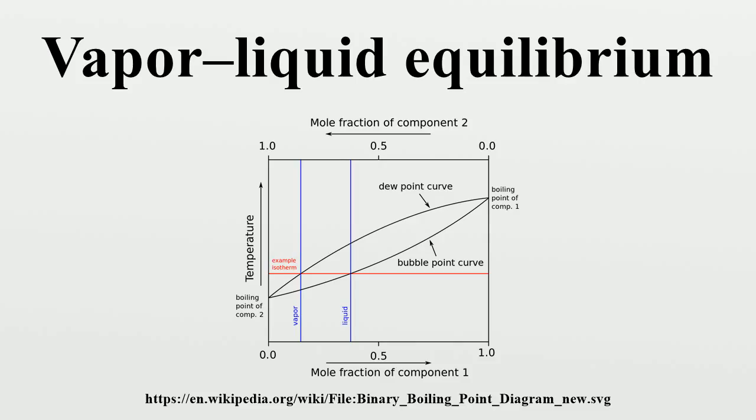When this is finished over a complete range of liquid mole fractions and their corresponding temperatures, one effectively obtains a temperature T function of vapor composition mole fractions. This function effectively acts as the dew point T function of vapor composition. In the case of a binary mixture, x2 equals 1 minus x1, and the above equations can be expressed as y1 equals x1 P01(T) over PTOT, and y2 equals (1 minus x1) P02(T) over PTOT.